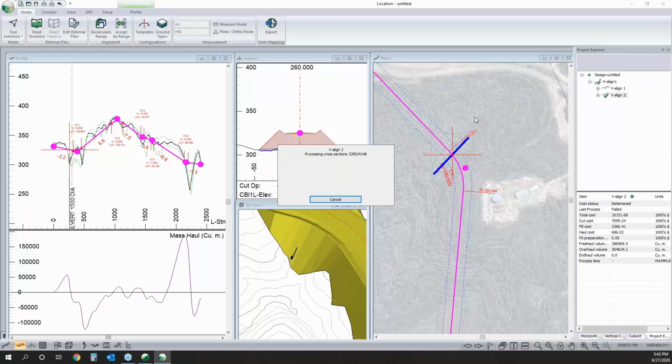Yes. So that comes into that composite surface thing that we just touched on. If you don't want to merge the surfaces, if you just want to see where something is for reference, you can add that into your separate views as well. So we added the pits in this for the plan view. We can also show where that pit surface intersects with our profile here and our cross section as well. But yeah, a couple different ways you can do that.